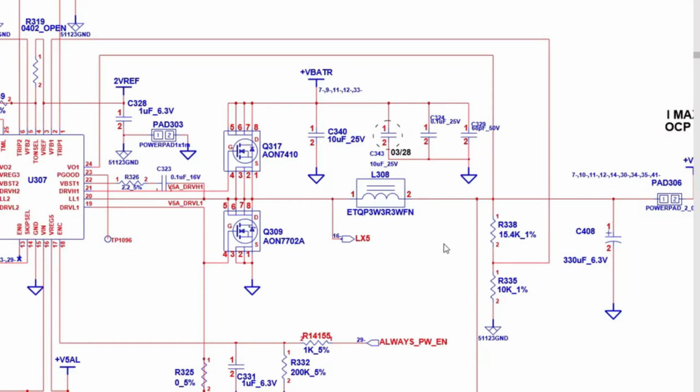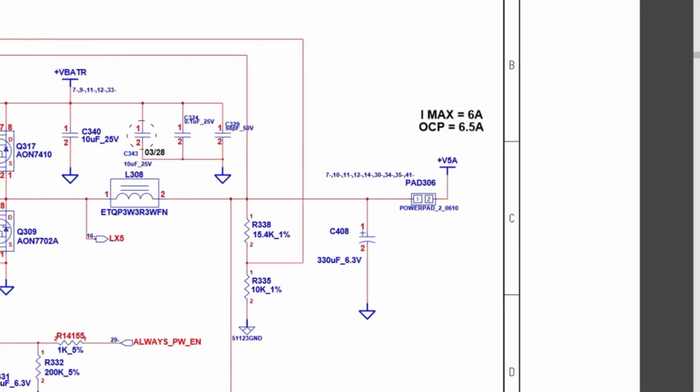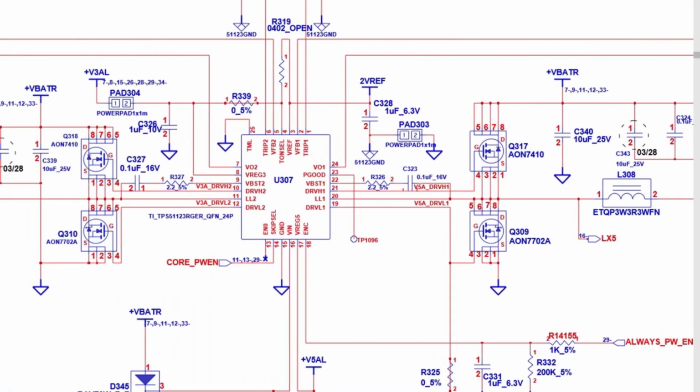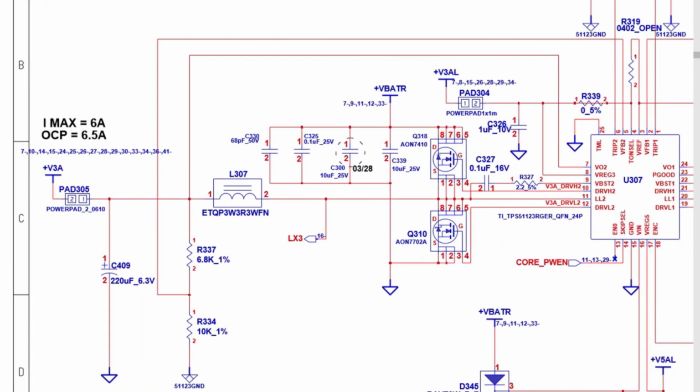As you can see here, we have the schematic. This is basically the 3 volt 5 volt circuit. Do you see? We have 3 volts here. Here we have the controller IC, 2 MOSFETs, an inductor or coil, and a capacitor. So here we have the inductor. Do you see? The inductor always exists in the power rail. No ground here.